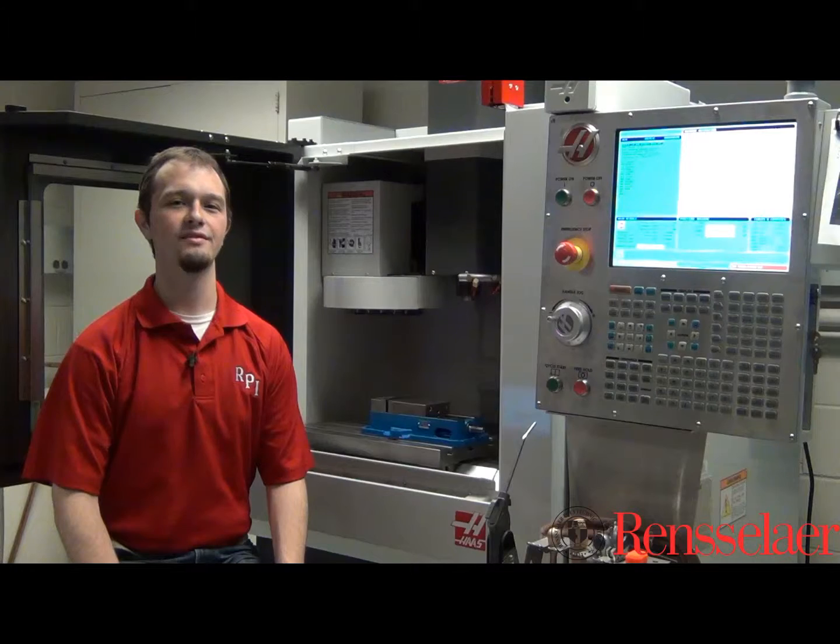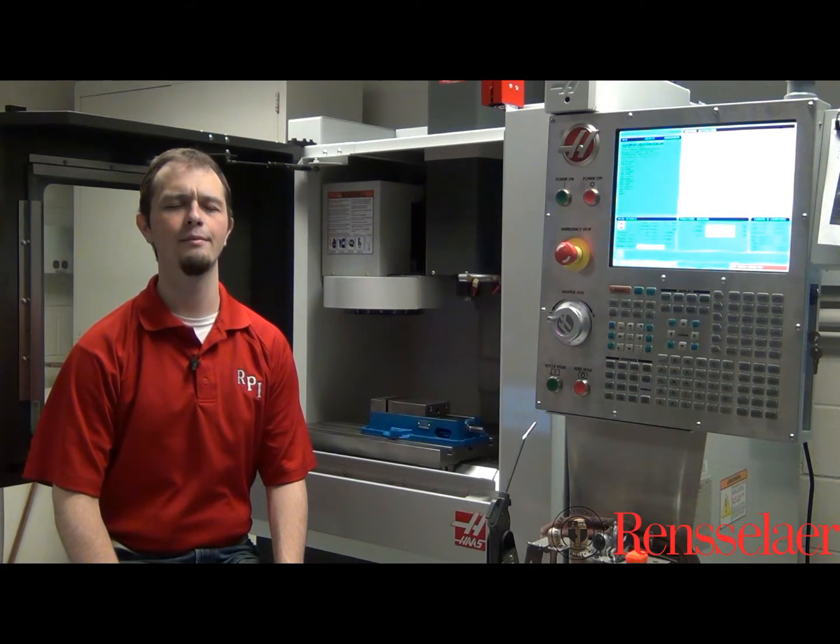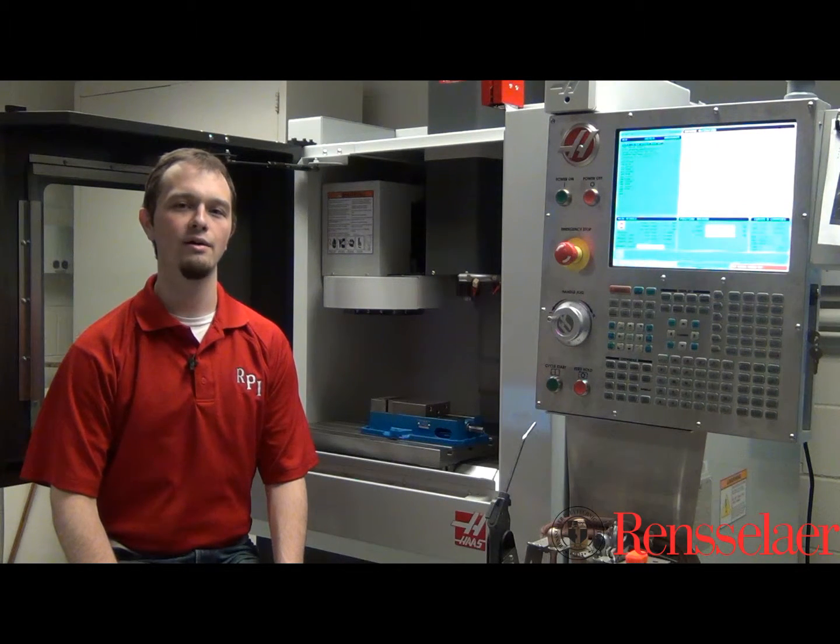As I mentioned on the previous slide, spindle speed is equal to cutting speed divided by pi times the tool diameter. At both the micro and macro scale, the cutting speed is dependent on the material and can be assumed to be constant. Therefore, the spindle speed is inversely proportional to the tool diameter. At micro scale, our tool diameters generally are smaller than 1 millimeter in size. Therefore, our spindle speeds can be on the magnitude of over 100,000 RPM. For comparison, macro-scale cutting processes typically range between 1 and 10,000 RPM.